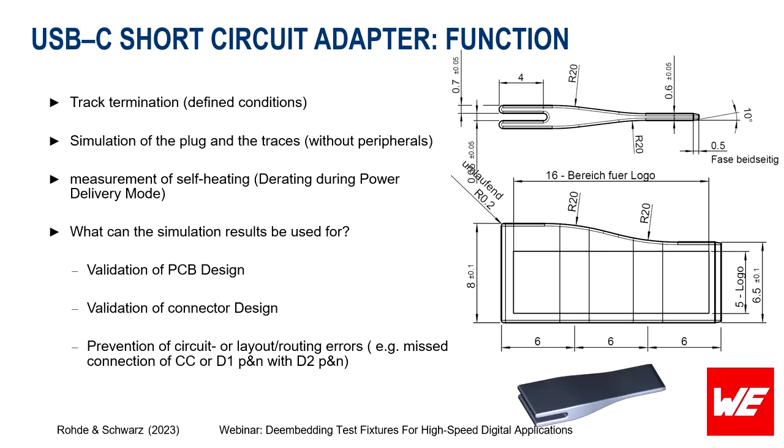The measurement can extend not only to data transfer, you can also test the derating function during the power delivery mode. This is important for us as component manufacturer, so we can test each component by itself: when we have the inrush current, how the derating curves look, what the maximum amps and voltage are that we bring to this connector, and what the heating curves are.